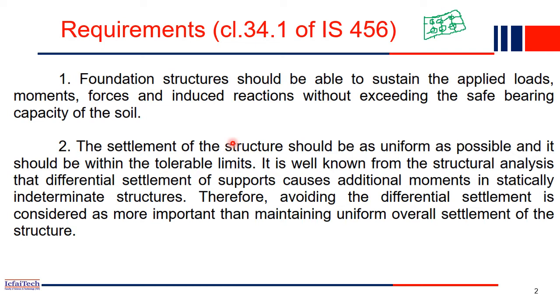So while constructing the foundation, you have to make sure that all the loads coming from the structure are taken care of. If the structure is designed for 15 stories, then you have to design the foundation also for the 15-story building. Maybe at present you constructed 5 stories, but the foundation should be designed up to 15 stories. So accurate estimation of loads is very important in foundation design.